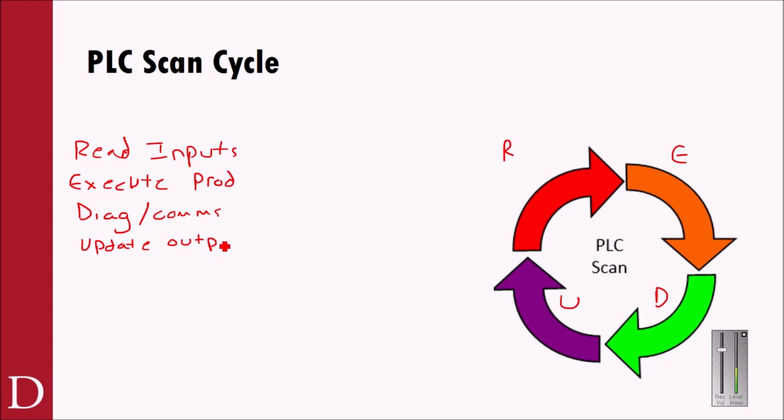And I might ask you something like, at what point do we know that a module is not working or something like that? Or at what point do we receive data from the HMI? Well, that's going to be during that diagnostics and comms phase. The read inputs is when I'm actually looking at those screw terminal inputs. The execute program is when I'm actually going through all of the ladder logic.